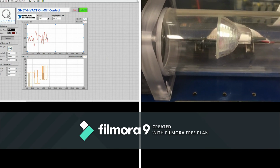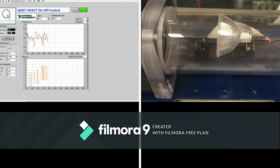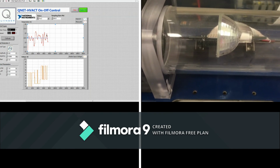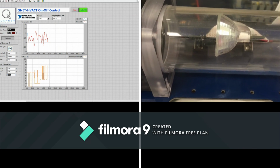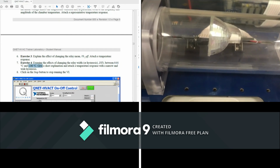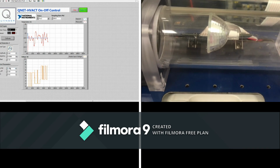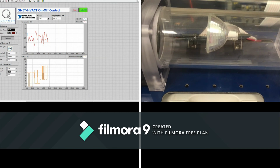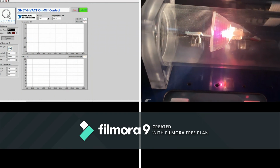So what is the allowable increase? What is the allowed overshoot? Can we reach 23 above 22.5? What is this limit? Delta TH controls this. In the manual it says to compare 0.01 and 1. If we have it very small, which is 0.01, let's go back to our readings. We can select any medium readings and we can start and calibrate.